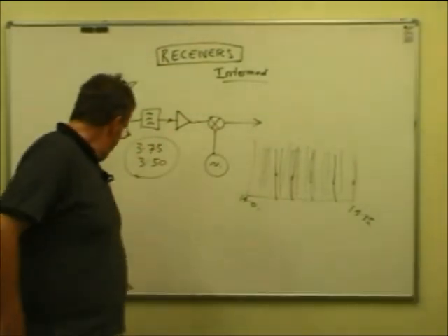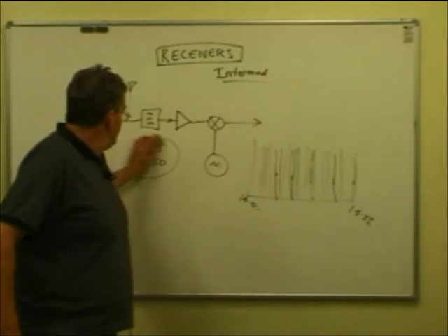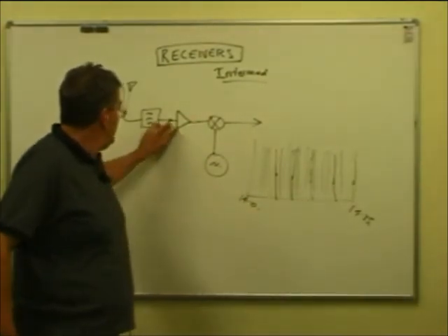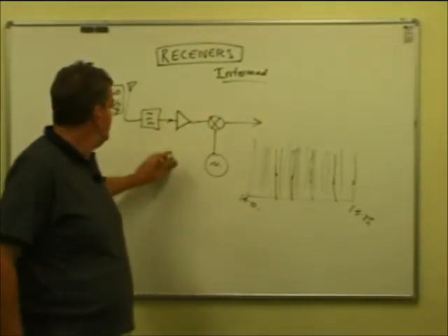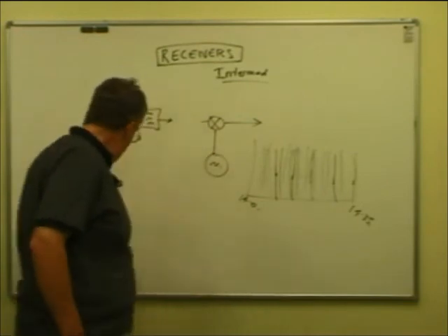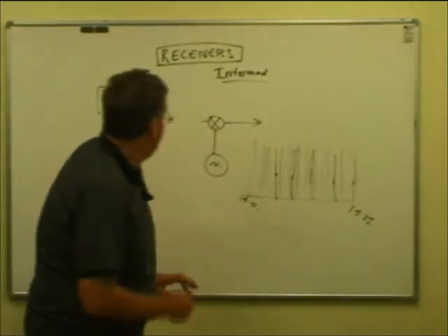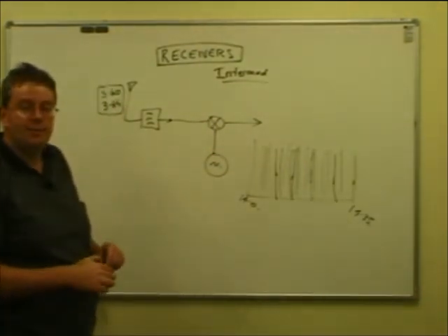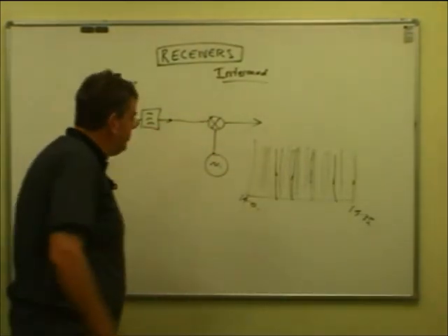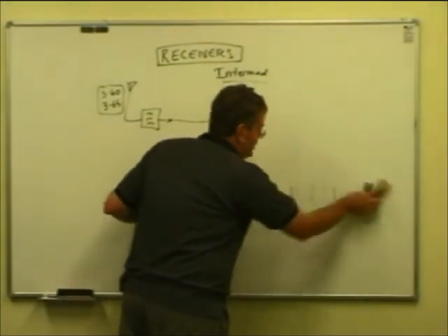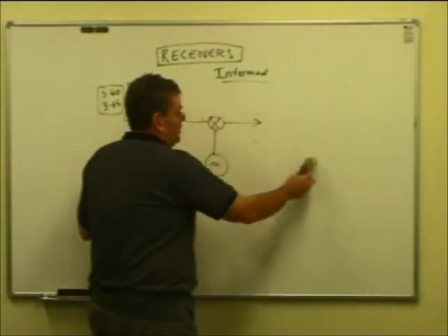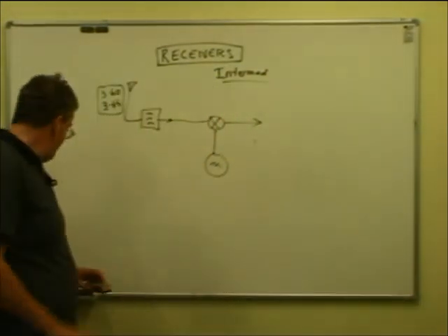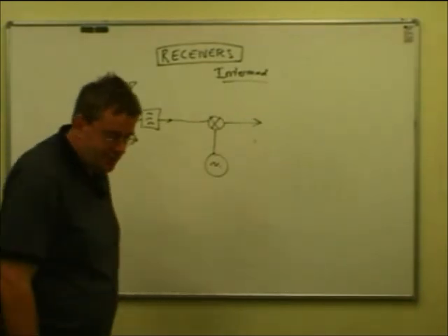And that was why I said on the lower amateur bands, where signals are very noisy, that this amplifier has very little to contribute, so you can actually switch it out. If you're in a contest on the 80-meter band with a lot of strong signals around, and you can switch out the front-end amplifier, you'll suddenly find that all those stray signals will vanish. You'll just be back to the few signals that you actually want. It's an interesting subject.